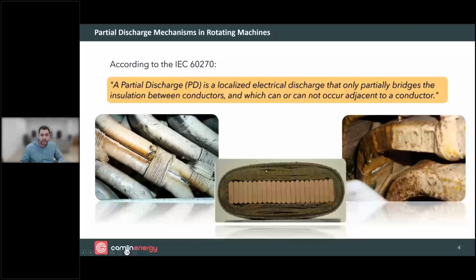And you can see here large voids in the material. And voids in the material would be like the void on the previous illustration. So these would be high electric field stresses at those sites, and we would have discharges potentially at those sites that may weaken the insulation over time if they're persistent and high enough of energy. And you can have a failure of the machine as a result of that.